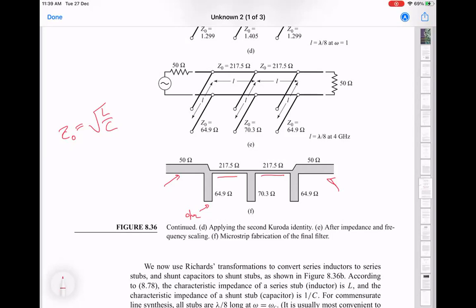We talked about two reasons, right? One is that when you want to make a very low characteristic impedance, then the size of your transmission line is going to get bigger because you're trying to increase the capacitance per unit length. So if you consider the microstrip geometry, then the capacitance per unit length basically comes from how big this is, because this looks like a parallel plate capacitor, right?